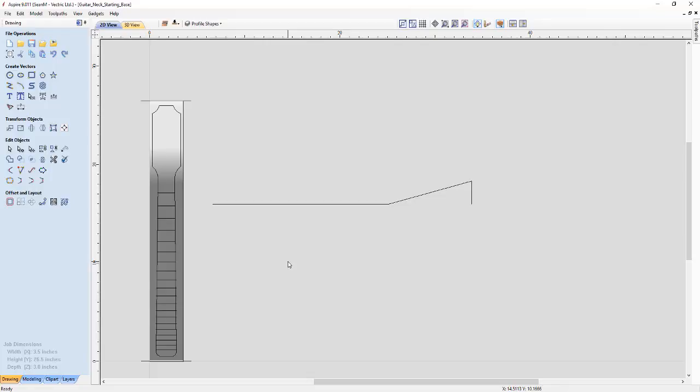And then we're just going to go ahead and draw some rectangles, as I find these are the easiest way to actually retain the height of our profile shapes. So we're going to start from the bottom up. So first of all, we're going to create the rail for our flat shape. So if we remember, that's going to be 1 inch high. So if we less 1/4 of an inch for the actual fretboard itself, we should end up with a height of 3/4 of an inch.